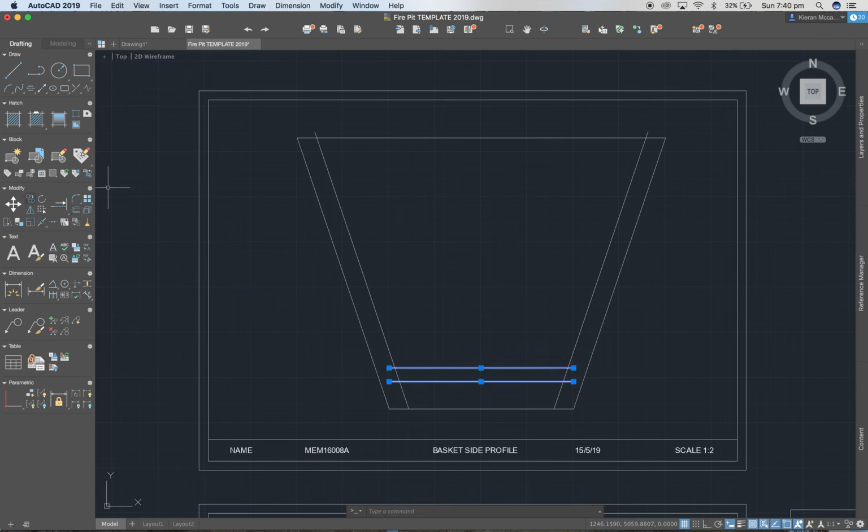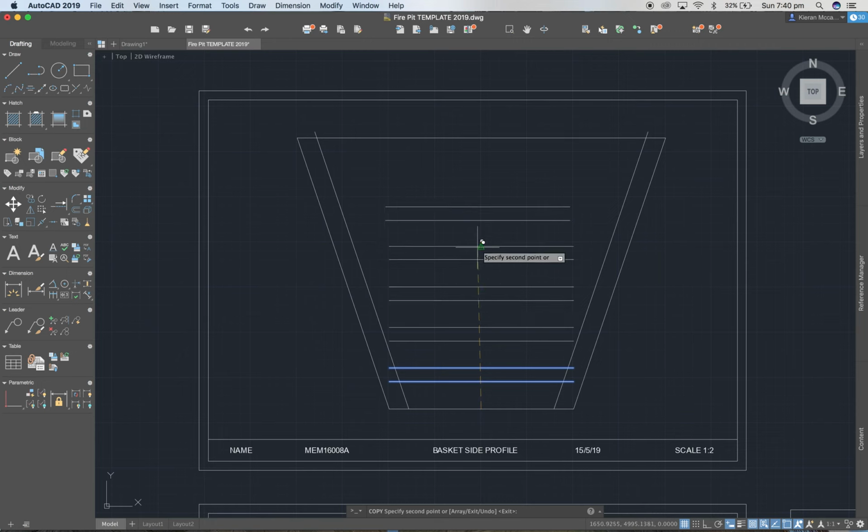and up here to where the copy tool is. And when we go to this page, we don't want to select anywhere. I want to select the midpoint at the bottom, and I'll show you why in a second. By doing this, if I select here, this will now give me a point, and all I'm going to do is move up to the second line, select it, up again, select it, and what I'm actually getting is all my pieces precisely spaced out, like so, and then that last one there, so we don't need to go up any higher. So when we've got them, that is what we're after.